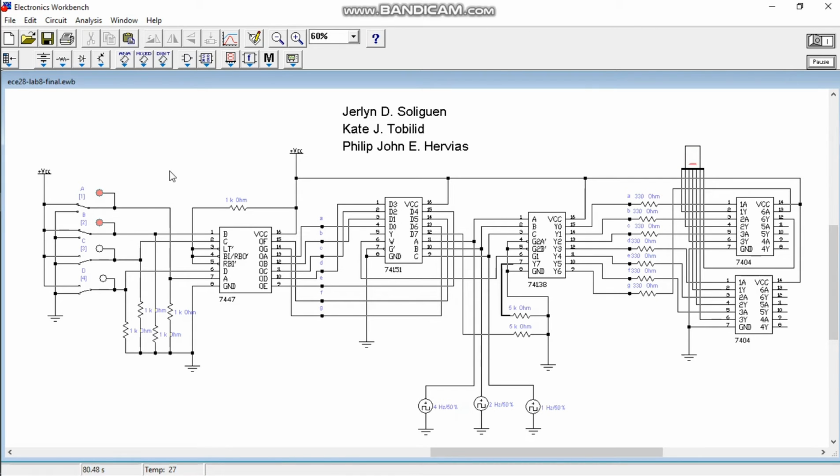If we try to put 0010 as BCD input in the circuit, the number displayed in the 7-segment display will be 4, because in this input combination, the segments B, C, F, and G are active.